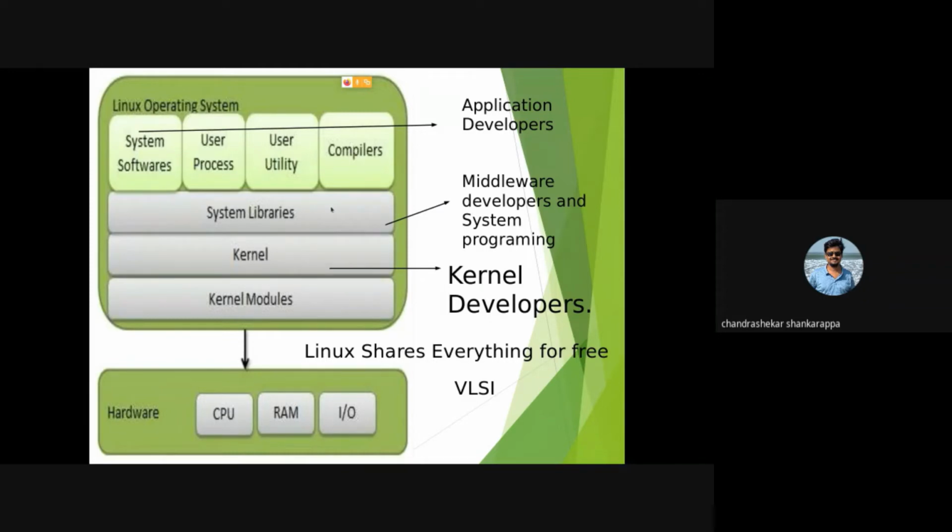So for example, can you guess how you can use the system libraries effectively in your code? libc is the standard library which has got the printf function. What you do while you are writing the hello world program is include a header called stdio.h, and then you call printf, right? Because printf is declared in stdio.h. So similarly, the kernel will expose some headers, okay, where some functions are declared. Those headers will be included in the applications to use the functions defined in the kernel which access the hardware.